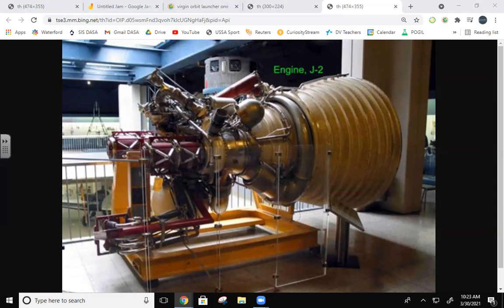So what solution did they come up with to keep the nozzle cool? In this case, you see these ribs. They actually flow liquid oxygen through these little pipes before it goes to the main pump, so it cools the nozzle as it's being used in the fuel. So the liquid oxygen is piped through these little tubes to keep the nozzle cool while the combustion is